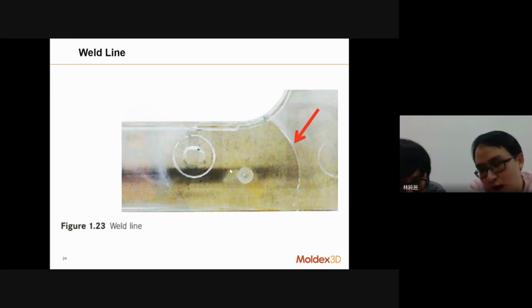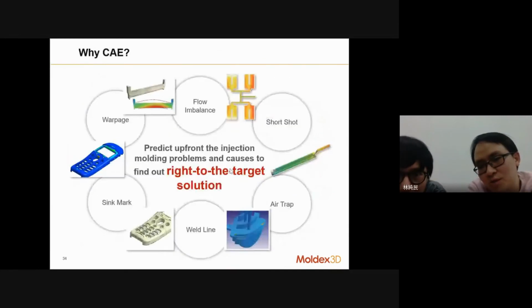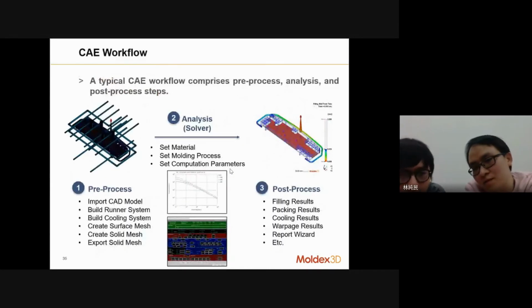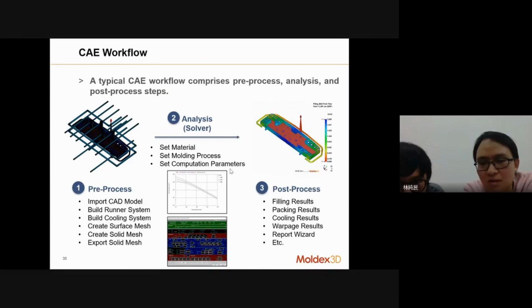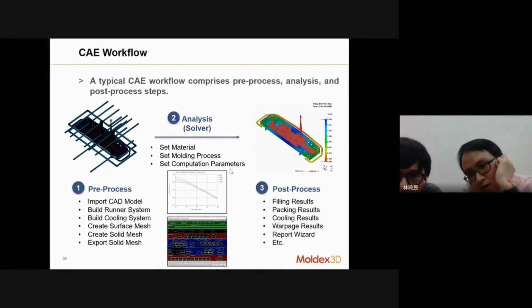So it will add more considerations while you are running the simulation. Okay, for example, it will also include the roughness of your pipe, and you also include how the flow streams in your simulation, to see whether the cooling gets stuck, maybe there is a vortex in there and so on. So you can include that when you run the simulation to increase the accuracy. Okay, and then about the setting itself, we have the setting user interface, so it depends on how you set that up. The things that you can set are, for example, the temperature, the flow rate of your coolant, and you can also set the type of the coolant. So all those are the things that you can set about the cooling system. Okay, so as long as those things are correct and just like in reality, basically we can expect that the accuracy will be high.